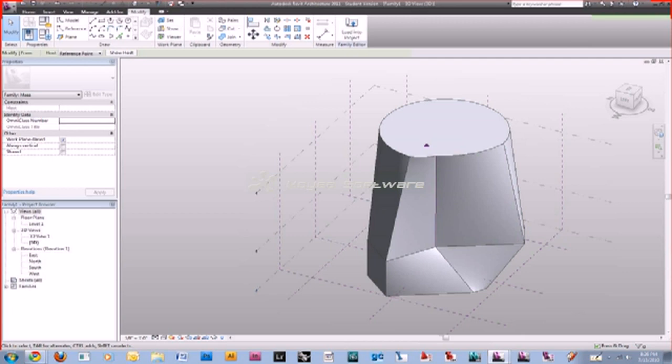Now this has multiple things you can do with it. Divide surface can either be used to help you place points and align things. It can help you create a custom window system, so you're not using just the boring curtain wall system inside of Revit and creating boring storefront mullions over and over again. You can add an actual component around that divide surface, whether it's on a polygon or a grid or whatever it may be.